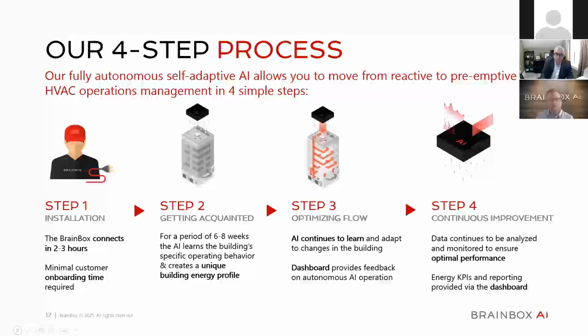And we have a building engineer review the control system, review the data, review what the AI is predicting. And he comes up with a subset of AI-driven algorithms to optimize that system based on its understanding. And so this is a multi-step process. He picks the algorithms. We work with the building engineer to set our thresholds, if there are any thresholds we need to set, and then we have a deployment plan. Then we go through that deployment plan.